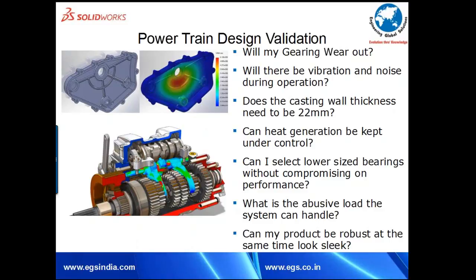One of the members pointed out that it is because, according to our design calculations, if the shaft size is 65, our engineers will, after taking into consideration the factor of safety, pad up on top of it and give it as the next standard shaft of 70 millimeters, and they will never touch the 65.